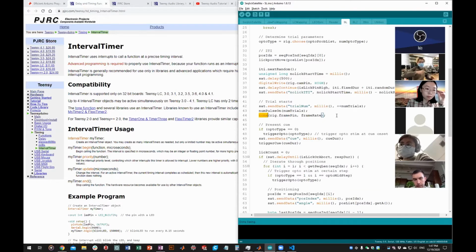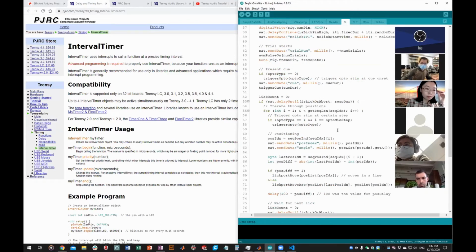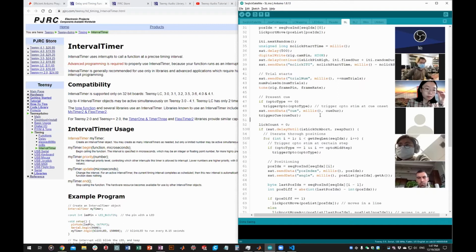Every time the timer reaches a certain value, it flips the 500 Hertz square wave, counts another period of time, and flips the voltage again, for each set interval by the timer. And we know for a fact that providing that train of square waves is not interrupting anything about the main code. So that's another example of how a timer can be fired up and used to control signals in parallel.